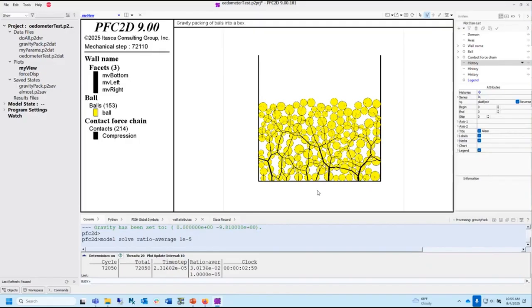Because in that granular system, the force on the bottom balls is always going to be the weight of the material. So if you just keep reducing stiffness, it's going to have bigger and bigger overlaps. The thing that controls how soft you can make it is making sure that overlap is maybe 5% of the disk diameter or something. That's a very typical thing.